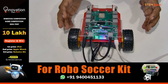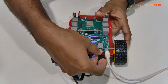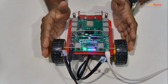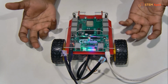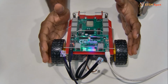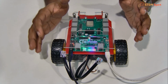Before uploading the code, you have to ensure that these cables are disconnected from the RJ11 ports, because these are connected to the motors. Whenever we use the pin numbers connected to the motors, direct power will be given to the motors and they will move away. To exclude that, we need to remove these cables first. We will use these motors in the next part. For this session, we are only using the LEDs connected here. Now let's upload the code into the board.